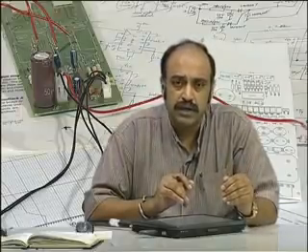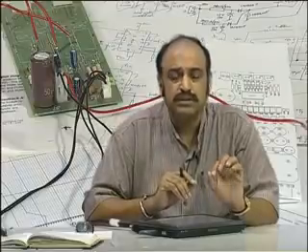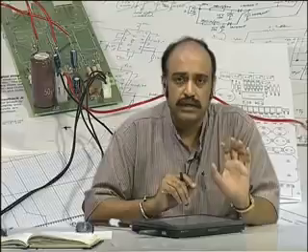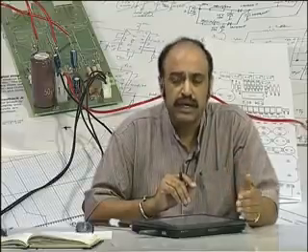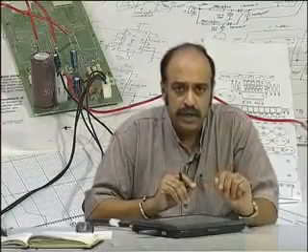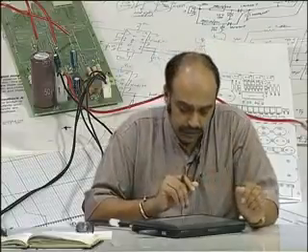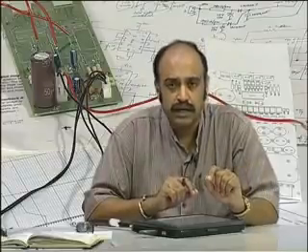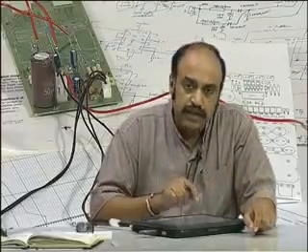In the case of electric circuits, if it is an inductor, the inductor current is a state variable, and if it is a capacitance, the voltage across the capacitance is a state variable. After having identified all the inductor currents and the state variables, mark them on the circuit.